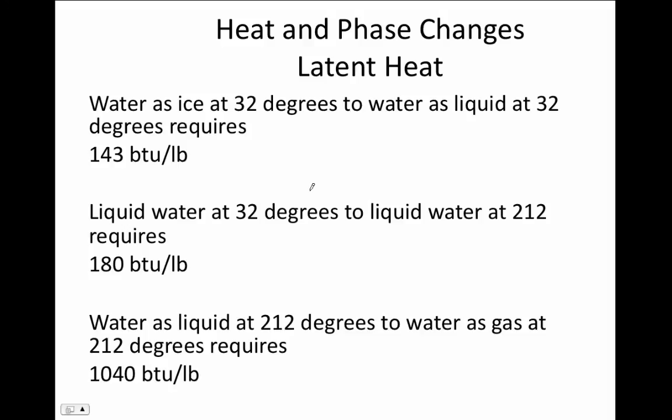Water, for example, as ice at 32 degrees to a liquid at 32 degrees, same temperature, it takes 143 BTUs to make that phase transition happen. It'll absorb 143 BTUs to melt ice.